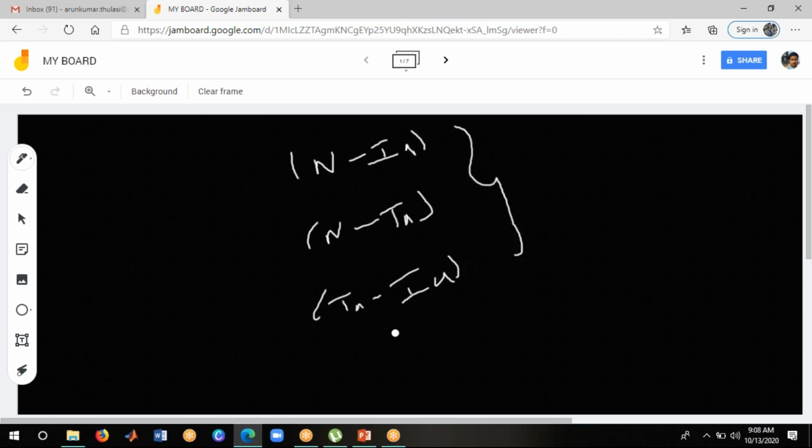Now in this class we are going to discuss every DC motor having these three types of characteristics and what type of DC motor is suitable for a particular application. Okay, I have already told you about applications. The DC shunt motor is used where constant speed is required, like escalators and elevators. And the DC series motor we use where high load is required. High load means cranes, hoists, like that.